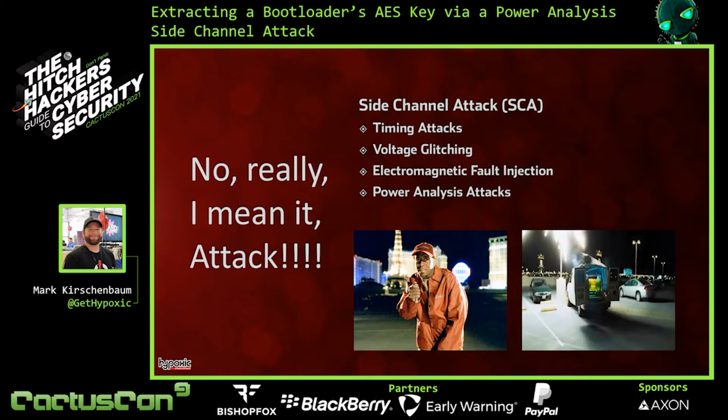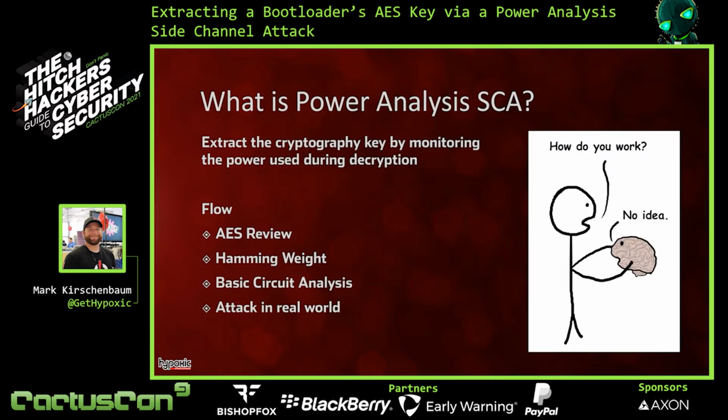But what was on the table was a power analysis attack, and that's what we ended up doing, and I was able to figure out the keys by this particular attack. What is a power analysis side-channel attack? Basically, all it is, we're going to be extracting the key by monitoring the power we're using during decryption.